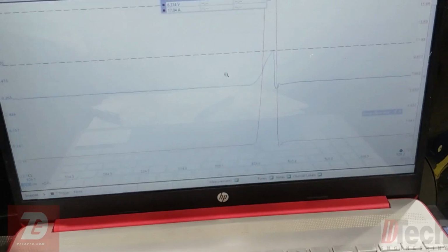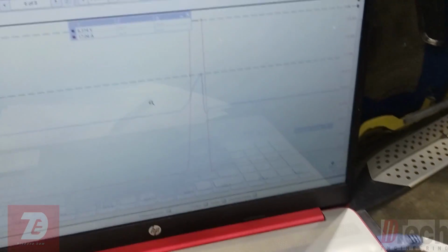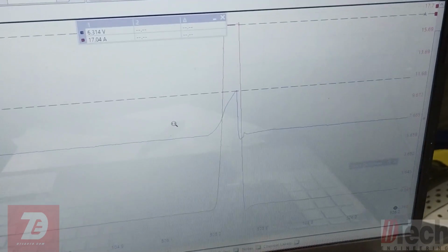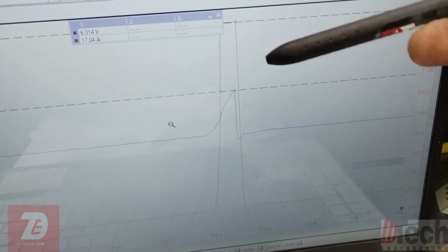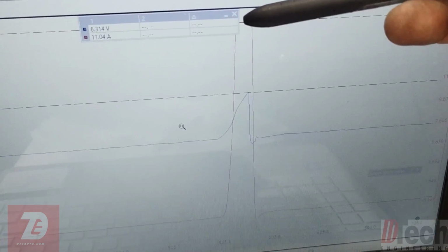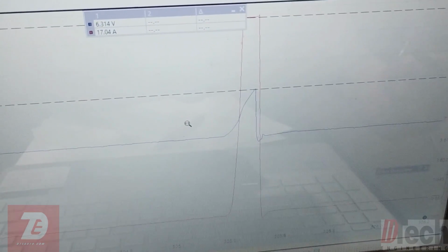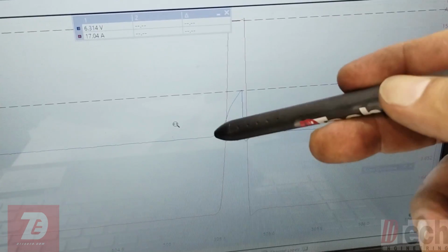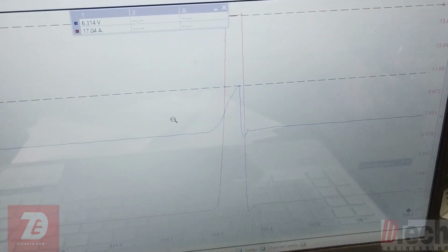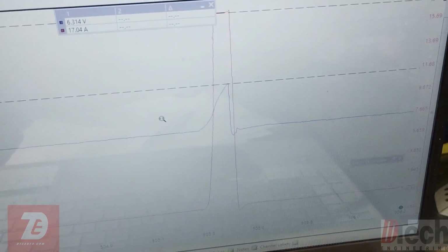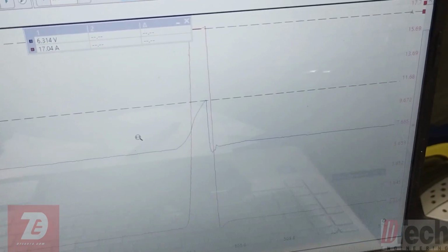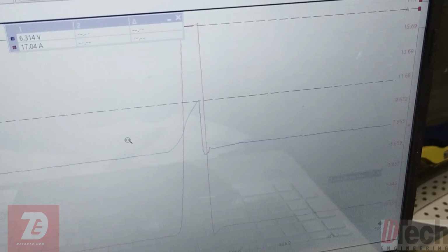Alright guys, so I got something to show you. We picked up on this and we know this shouldn't be this way. We should not have 17 amps. And it's not like it spiked up and then the rest was lower than that, so not an inrush type of deal, like an electric motor or a fuel pump or blower motor.